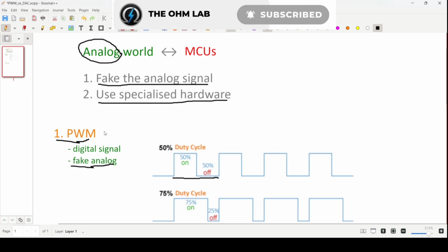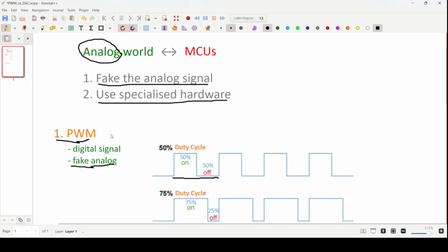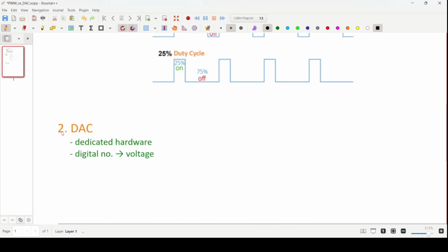Now the question arises, can we turn the noisy PWM signal, noisy because of fast switching, into a DAC-like signal? And the answer is yes, we can do so with the help of a low pass filter.